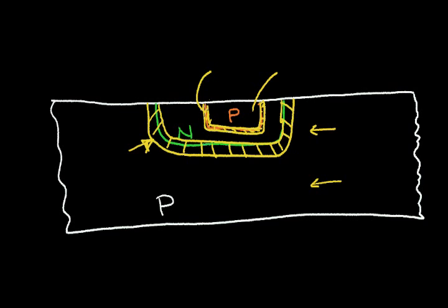So for the same amount of area, I get more capacitance in this upper junction and less capacitance in the lower junction. And also, I can infer something about breakdown voltage. This depletion region here is wider, so it will have a higher breakdown voltage. In this top region, this junction, this depletion region is narrower, and it will have a lower breakdown voltage.